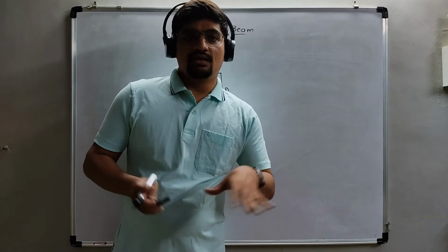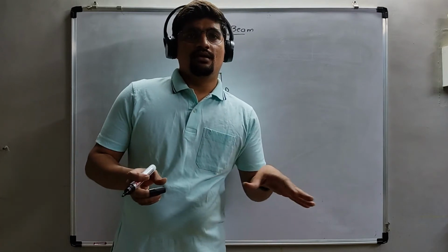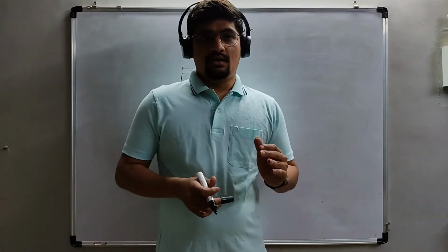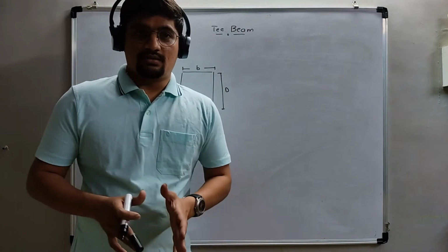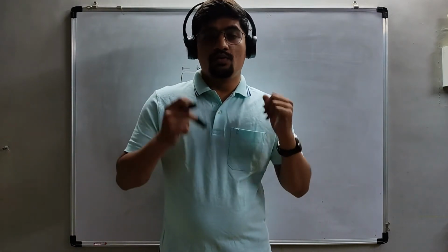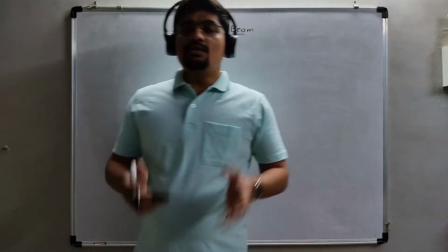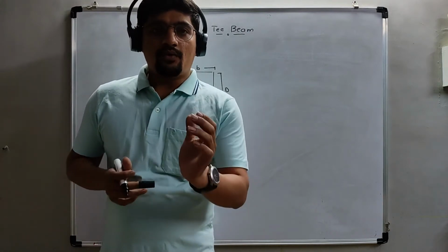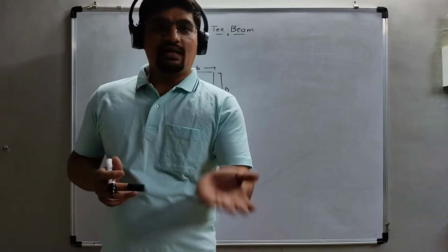Sorry, I mean the limiting moment. If I am taking a beam section of 250 by 400 mm, the size of the section can only resist a moment up to 100 kilonewton meter. But after calculating from the load, the moment occurring was 180 kilonewton meter. So it means that the section may fail. Therefore, we provided another type of section, like the doubly reinforced beam.